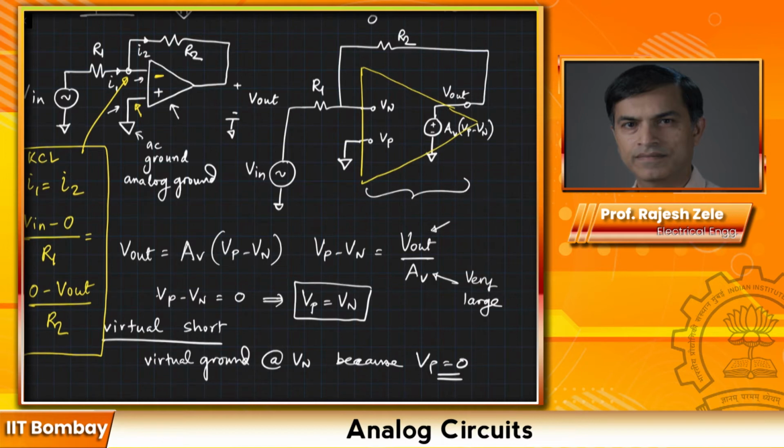It's important to note the direction of the current whenever you're using your KCLs, KVLs, and Ohm's law. Just make sure that you don't make a mistake, one silly mistake, and you will get a totally wrong answer. So make sure you get the flow of the current and the potential difference always in the correct direction.